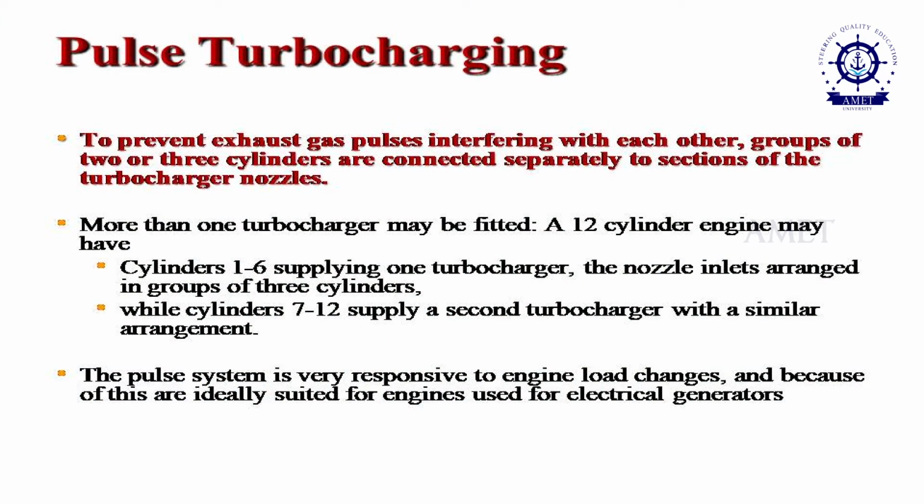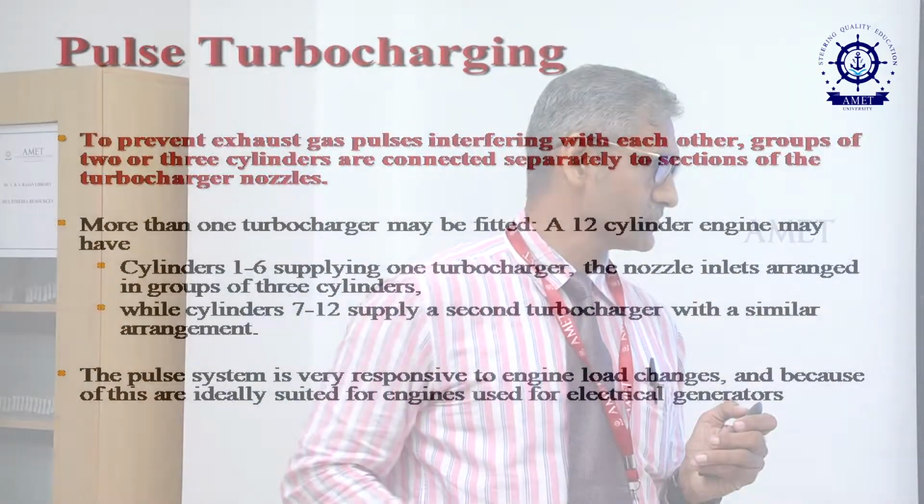The reason why the pulse system used to be very popular earlier is that it had a very special advantage, because you are using the kinetic energy of the gas as it is moving through the cylinder. So, all the energy in the exhaust gas gets immediately transferred, which means whenever an engine load increase is needed and the engine speed increases, my turbocharger automatically responds and increases the speed of the turbine, which means I will get more air. So, the beauty of the pulse system is it will always be responsive towards the engine performance.